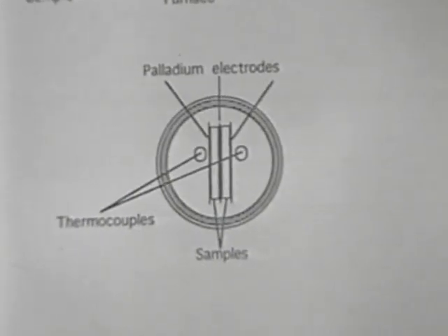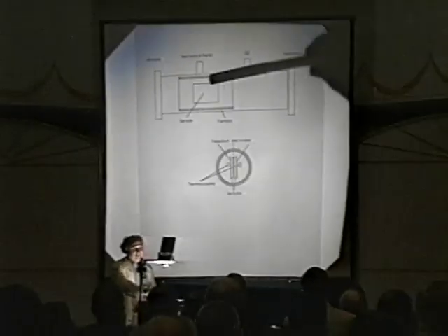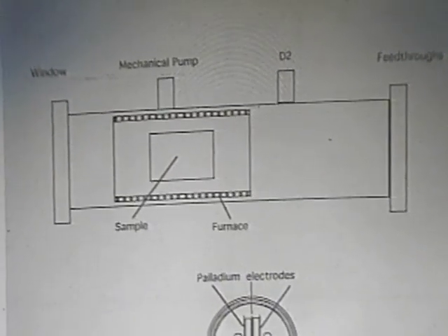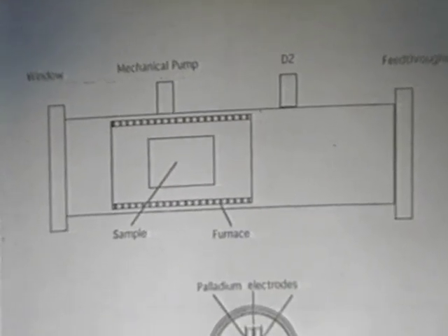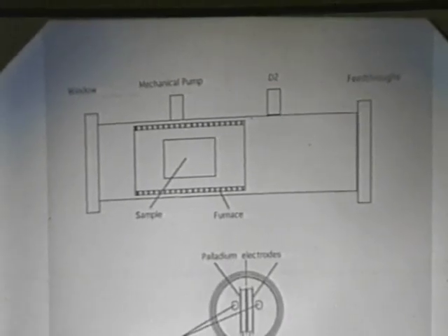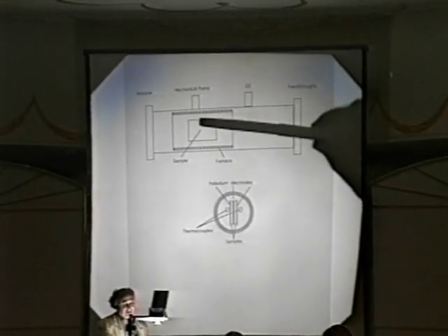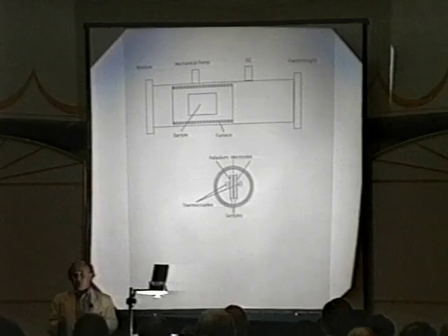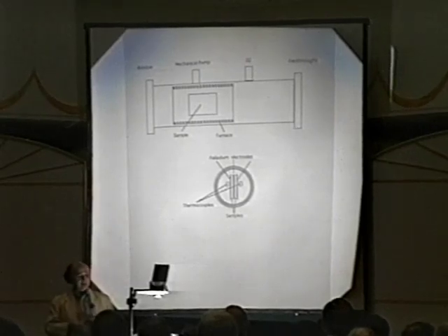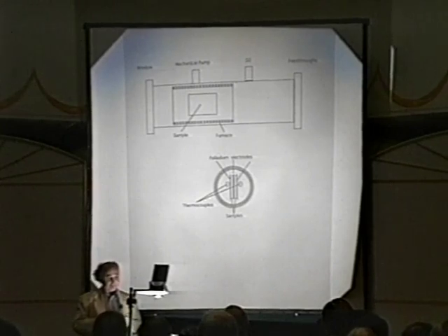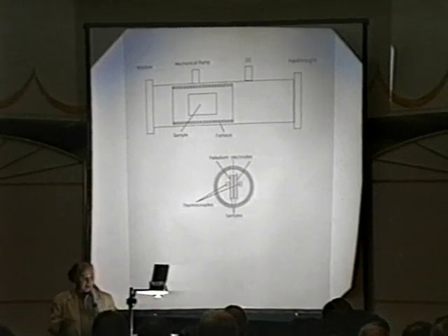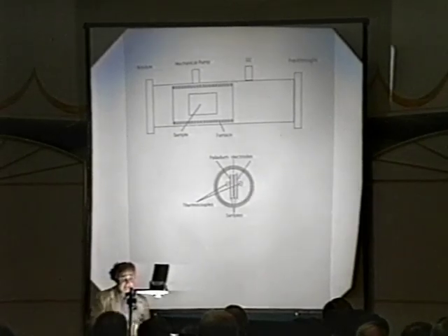We have calibrated. Also, we have a third way of measuring temperature, which is slightly odd. We measure the resistivity of the heater. Because, as everybody knows, the resistivity of a wire varies linearly with temperature. So we calibrate, we work at constant power. And if there's any heat generated inside the crystal, the resistivity would change. By measuring simply the voltage across the heater and the current, we can determine the resistivity and therefore the temperature. So we have calibrated this resistor with the thermocouples. And we measure the temperature rise when we put current through the sample.